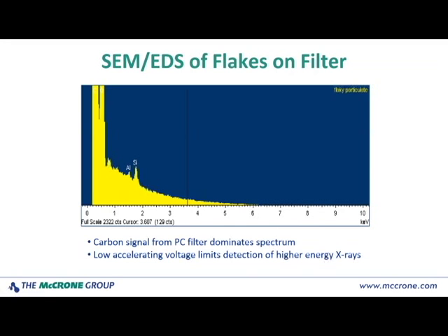So if you had already done polarized light microscopy and looked at the morphology of this flake using the stereoscope, using the SEM, and you were seeing things that were very typical of glass delamination, this EDS analysis in the SEM might be conclusive enough. But if you had a residue, a glass coating, a secondary product, there's really not enough information in the spectrum to make conclusions, simply because most of the signal that you've gotten going into the spectrum has not come from your sample.